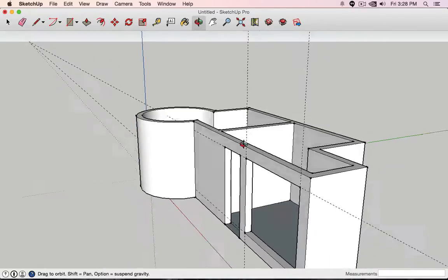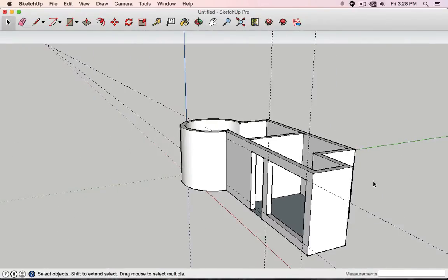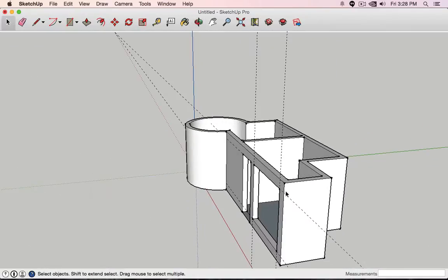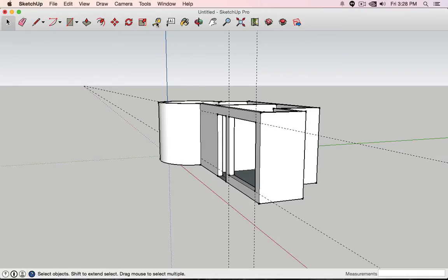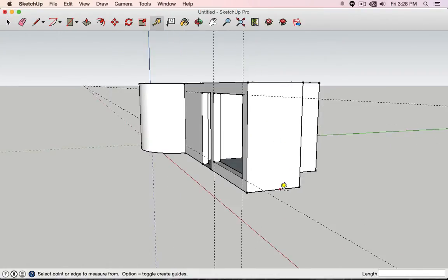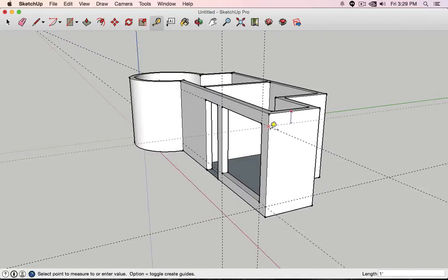Pretty nice. So let's say on this face I would like to do exactly the same, another foot and foot distance, but the same height and the same bottom part. So on here I can click, drag up obviously 1 foot and enter, so it's the same, but I could also drag it up, go to this vertical edge, slide along it till this edge intersects with this guideline, and there's my height. Same here.